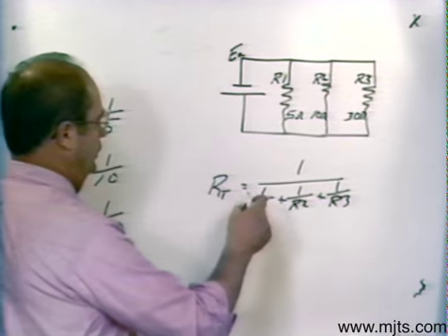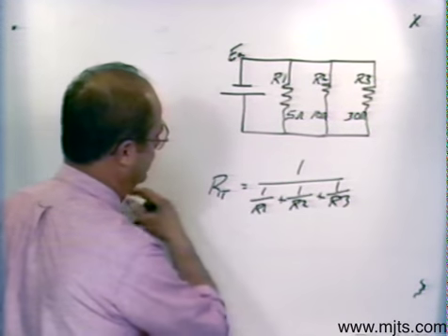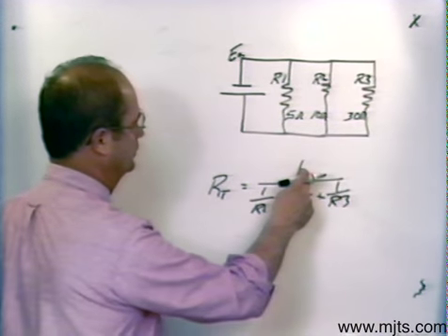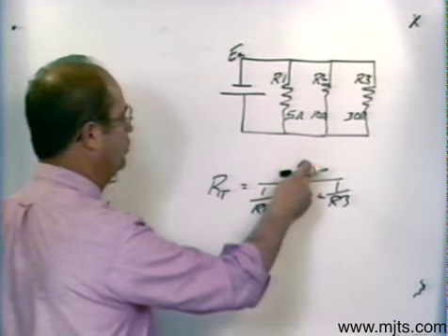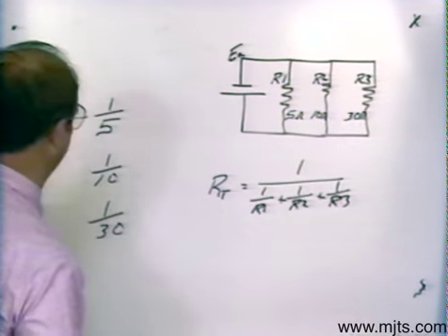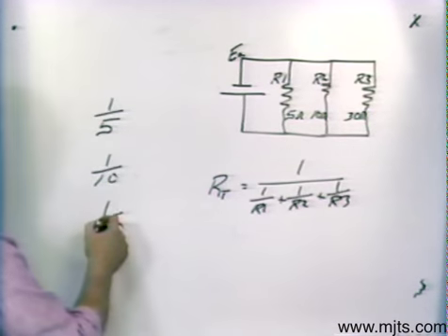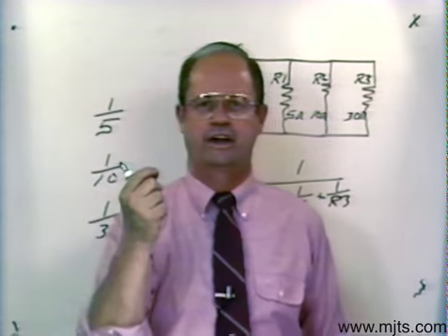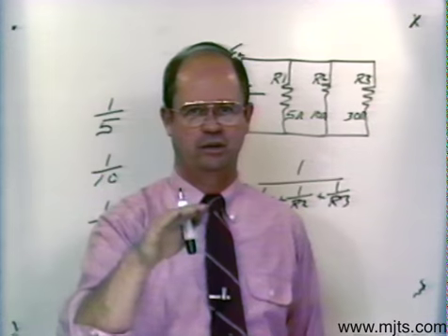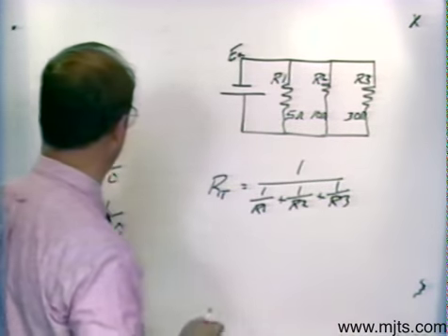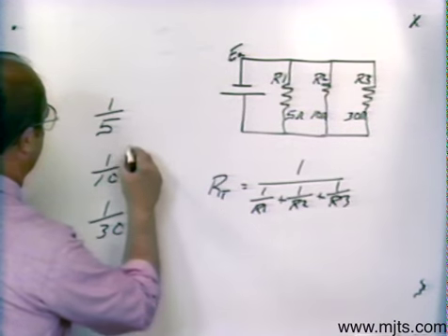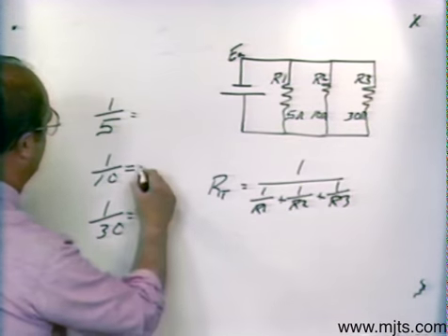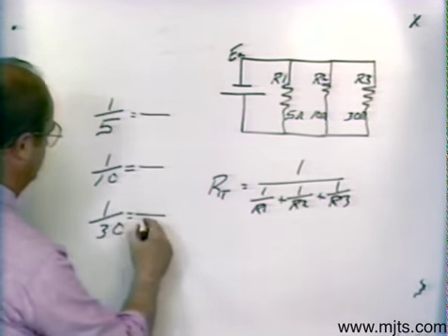What we have to do here is find reciprocals, like I've done, add them together, and then take the reciprocal of it again, or divide that value into 1. Okay? Now, I've made reciprocals out of these. You'll remember that in first year when you had fractions, before I could add those fractions, they had to have the same common denominator. The common denominator, in other words, the number that would be divisible by all of those numbers, would be 30.